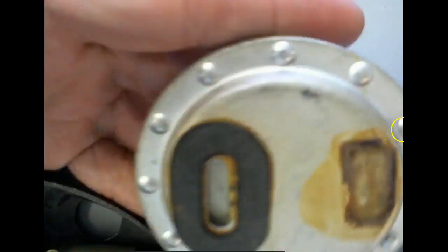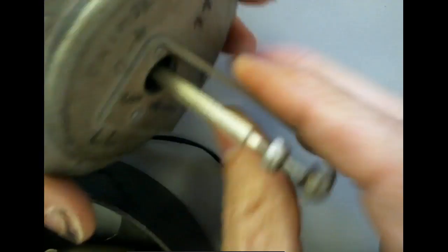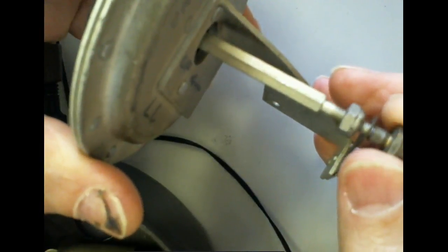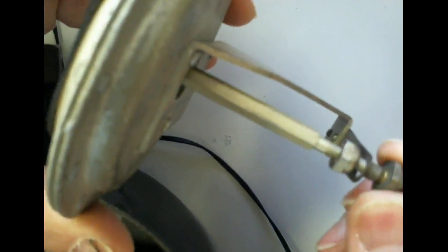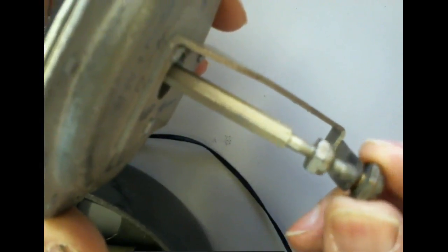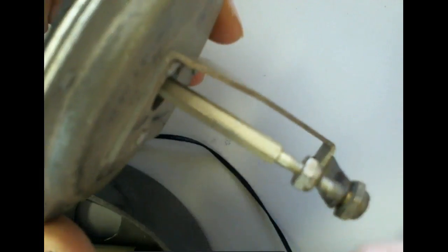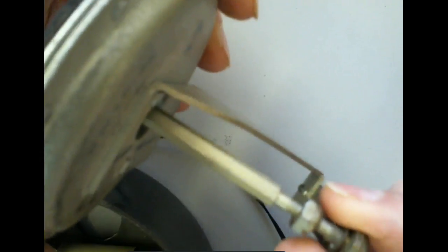You understand that? This is the flat diaphragm right here. And of course the diaphragm is in there. But when pressure comes in through this outlet, it causes the diaphragm to do what? To move. And this is where we would attach our sensing element, right out here. So I could attach a potentiometer out here, right? You understand that moves with that, a linear potentiometer, or I could attach a little limit switch that hits up against it and makes a limit switch and get a digital output.